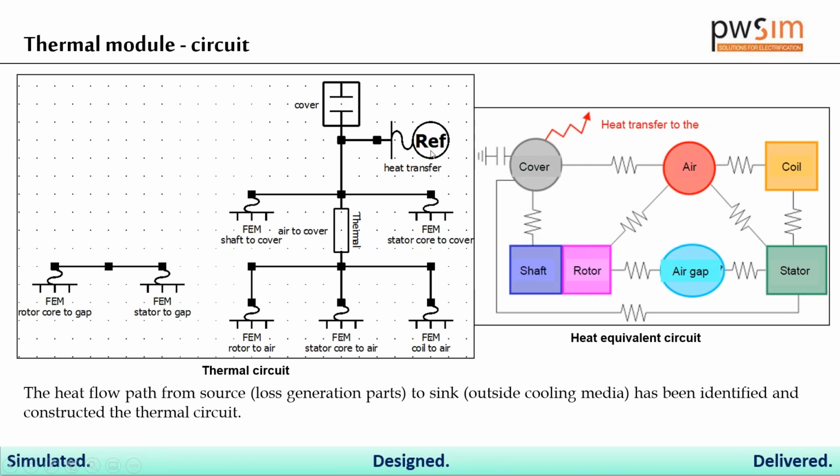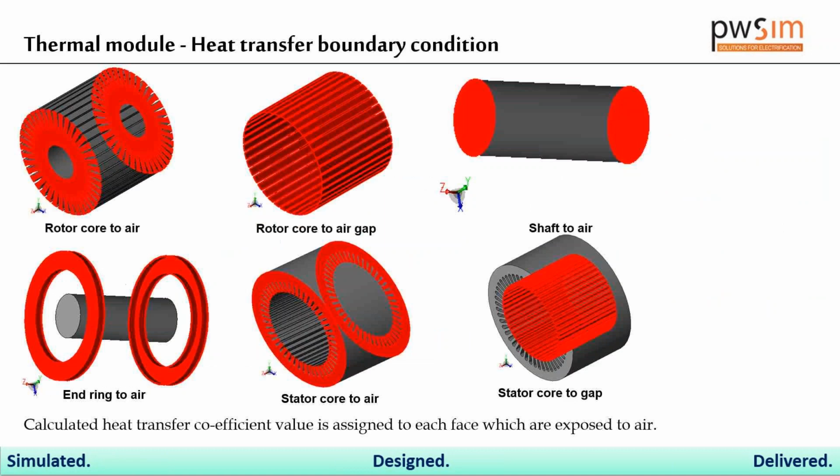You can give some reference temperature value here, and based upon that you can finish your thermal circuit. In most cases the thermal circuit will be similar in most of the motor types. Only a few changes will be there here and there. But if you are doing a completely new design, you have to reframe the entire thermal circuit that is available. Okay, so this is about the thermal circuit model.